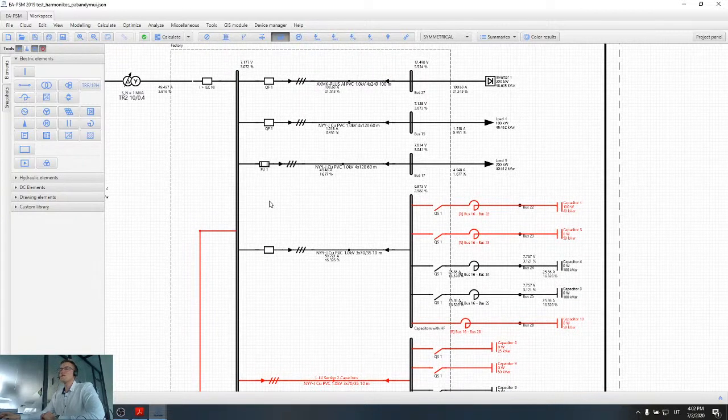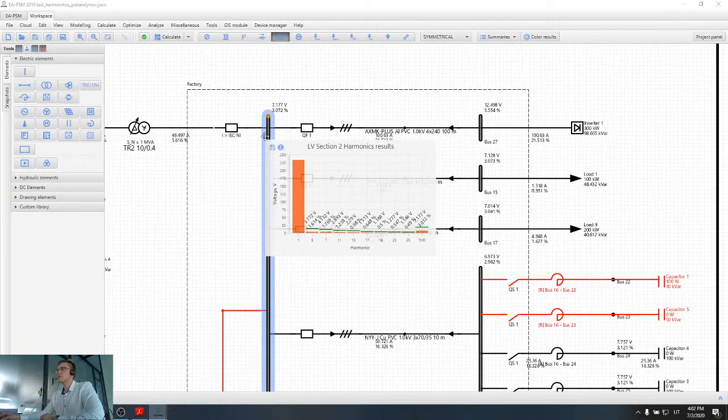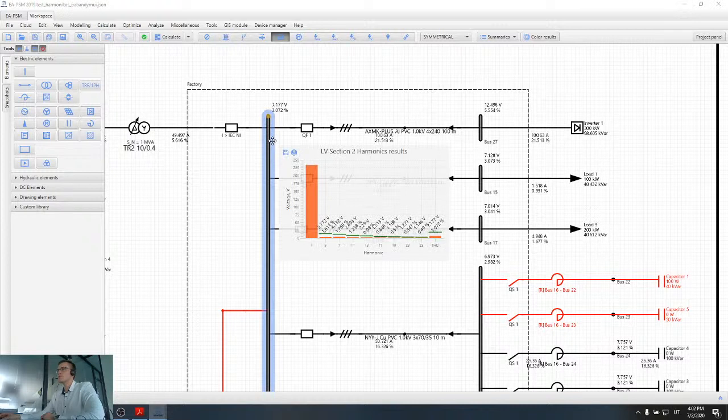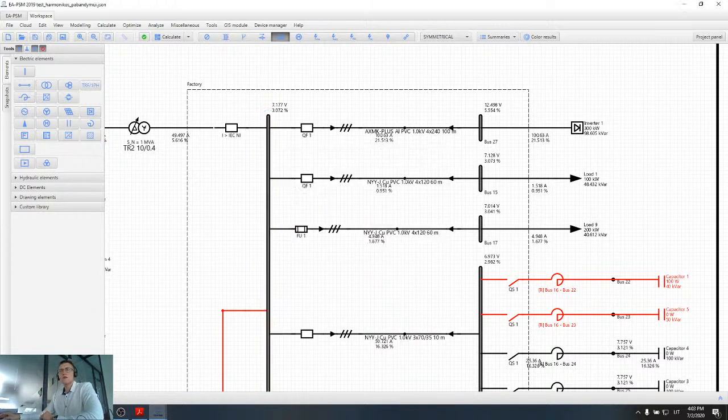Also, the reason behind this is that those higher frequency voltage harmonics are usually not that big. For example, if we take this bus bar, we can see that the first harmonic is 230 volts. This is the normal 50 hertz frequency harmonic, and other harmonics are all smaller than like 4 volts, 3 volts, so very small, and those small harmonics do not affect the RMS value too much.